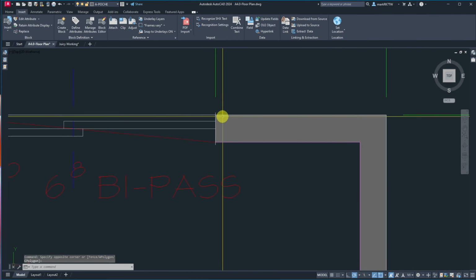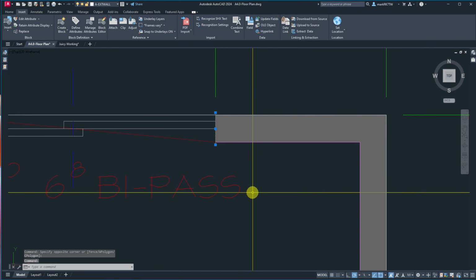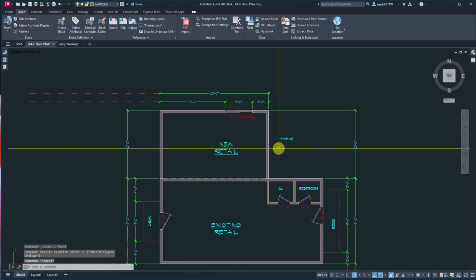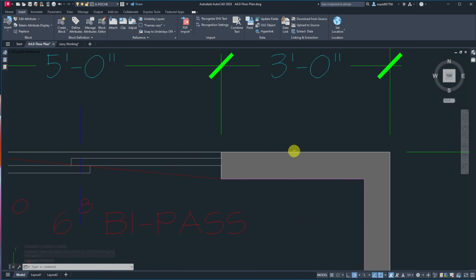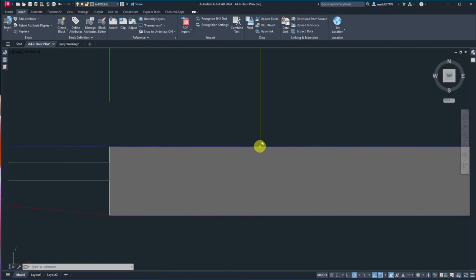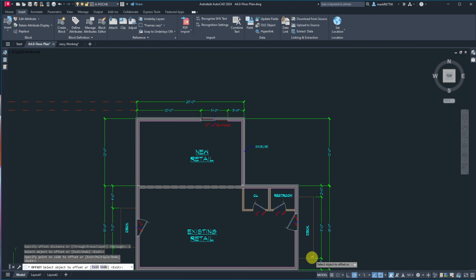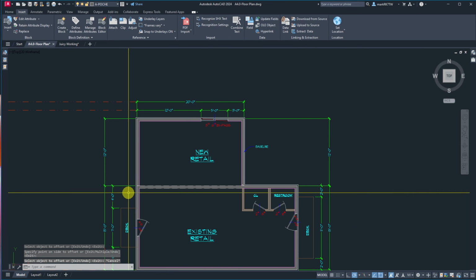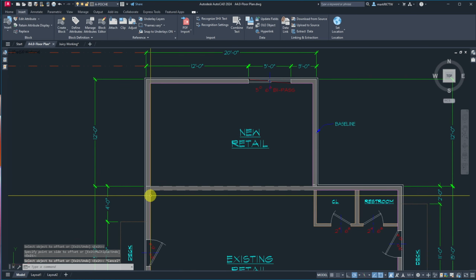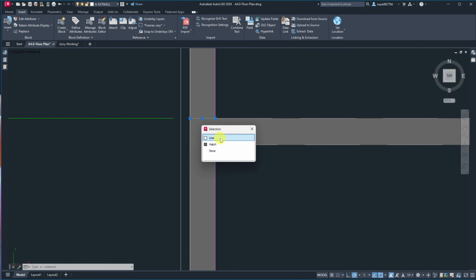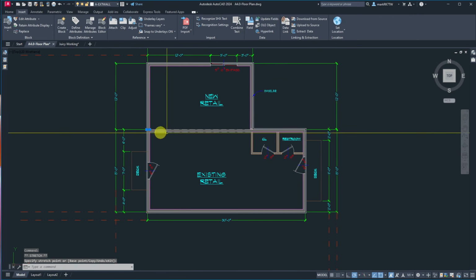This looks odd that that's sticking out. I wonder if I can delete that, and if there's a line under it. There is one. Okay. So if I'm going to insulate this outwardly, I'm probably going to end up with like a 2-inch. So let's offset 2, because all the new will have to have that. But this existing, I don't need to do that. So we have to figure out what's going to happen with the transition here. Because in our existing building code, I won't be required to update the new.